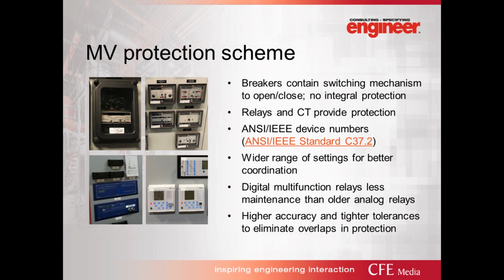So I'm going to talk a little bit about the differences between low voltage and medium voltage equipment. And I think the major piece that's different is the protection scheme. Unlike low voltage, the medium voltage breaker contains only the switching mechanism to open and close the breaker. It doesn't have any integral protection built in. That integral protection is really provided by separate relays and CTs.